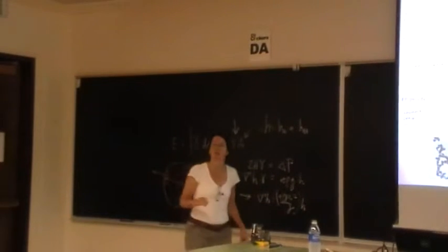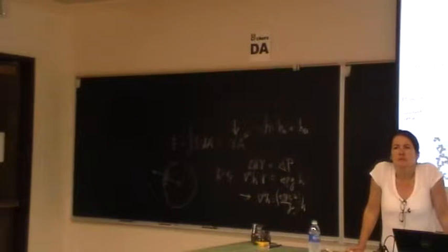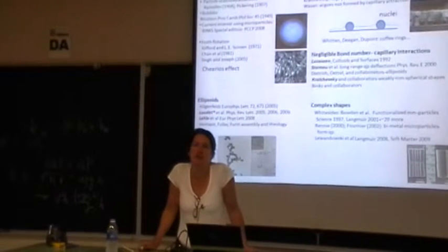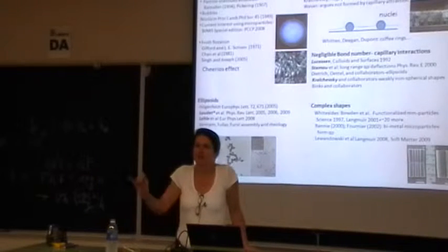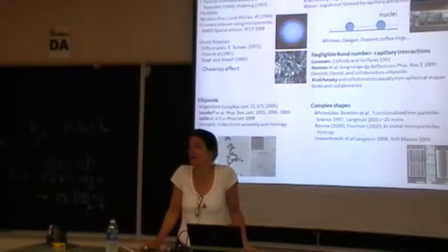You have a question? You mentioned that the evaporation flux is higher at the contact line. Is that just because it's more highly curved than the rest of the droplet? It's because we have a flux surface adjacent to a no flux surface. It's akin to the divergence in viscous stresses at three-phase contact lines, and the problem with the charged disk in electrostatics. He will always supply the electrostatic analogy, which I'm very happy to have you do.